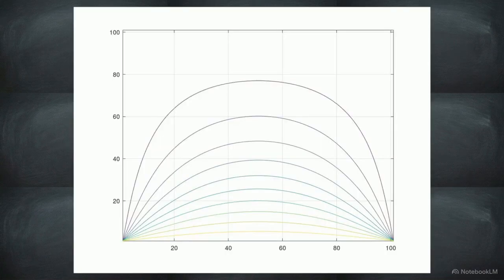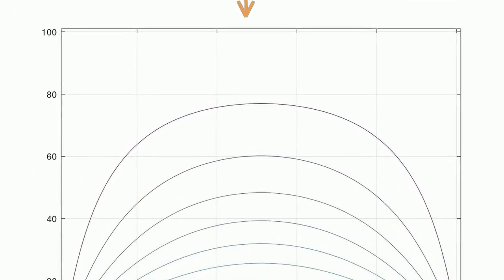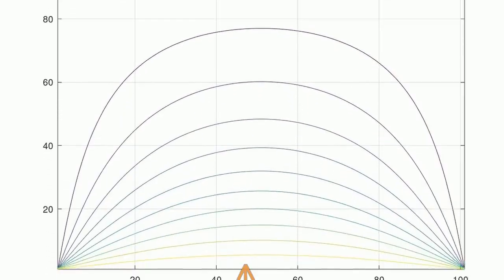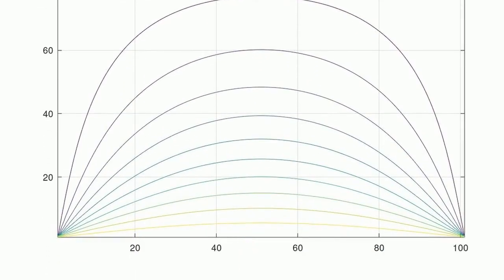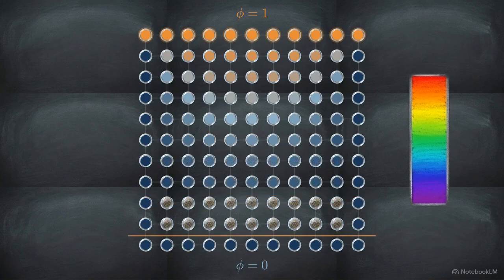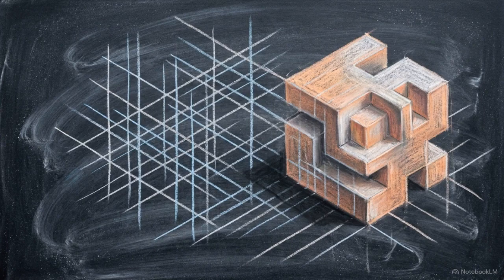This plot shows the partitioned cavity flow output. Notice the 0 constraints along the vertical edges and x-axis. The simulation draws energy from the single unit boundary on top. Concentric gradients curve smoothly from that active boundary into the base. This continuous scalar field represents the calculated values of all the internal nodes that were previously unknown. Seeing these gradients proves that our single boundary constraint successfully propagated through the internal algebraic equations. The cavity flow contours prove matrix partitioning works. It turns an inert, self-canceling global matrix into a solvable, physically meaningful simulation.